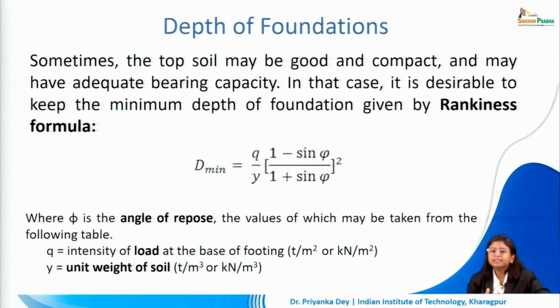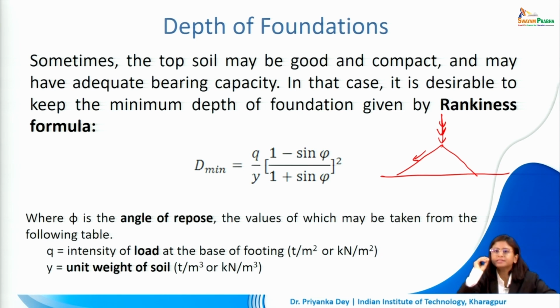Angle of repose is a particular angle beyond which any loose material, any granular material, if it is piled, it will start slipping. So let's say on a construction site, you have started piling sand and you have placed it in a bit of a mound, like a little hill. So there will come a point, if you keep pouring sand on top of it, where it will start slipping. This is the exact angle which is called the angle of repose. So right at the point when the slipping starts happening, that is the angle of repose.